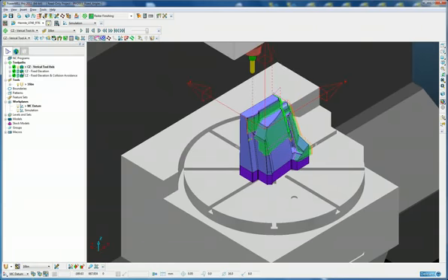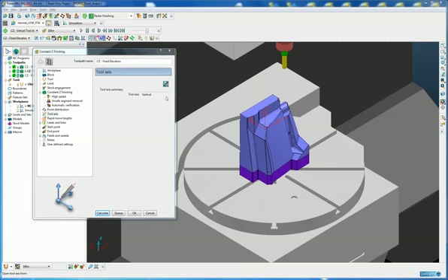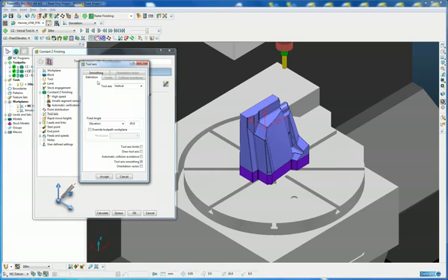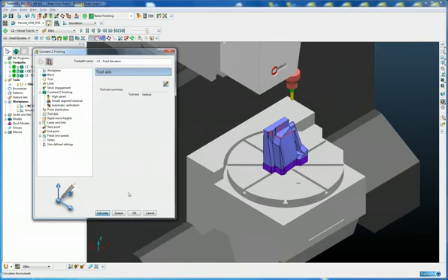So now we're going to use the new fixed tool axis option to force the head of the machine over at 45 degrees and lock one of the axes of the machine. So if we go to the settings for our second toolpath, on the tool axis form there's a new option under the definition tab. You see our tool axis is still set to vertical, so 3-axis machining, but then we're telling it to lock, in this case, the elevation angle to 45 degrees. So in this case the elevation angle is the B axis, which is on the head. If we accept and calculate this toolpath,